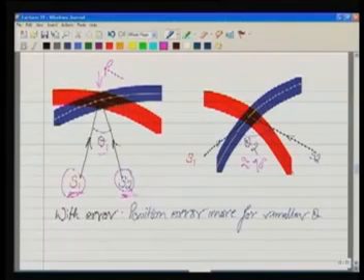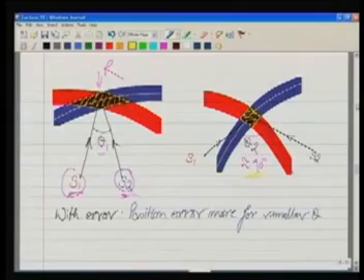What do we observe from here? The interesting observation that we can get is, if the angle is small, the area of uncertainty, we are showing it graphically, the same thing can be shown mathematically also. That's the area of uncertainty, and over here in this case, this is the area of uncertainty. So, when the angles are around 90 degrees, the uncertainty is less. So, this is why we say the angles should be nearly equal to 90 degrees.